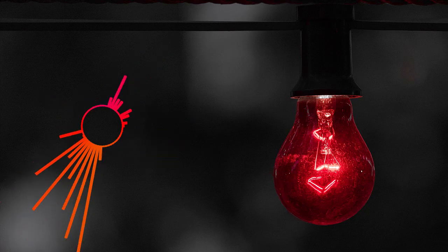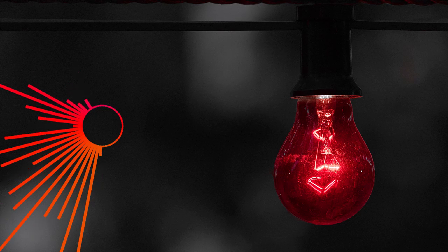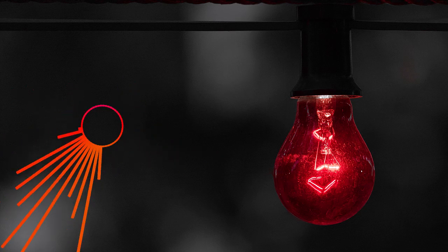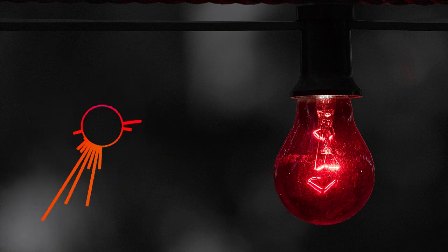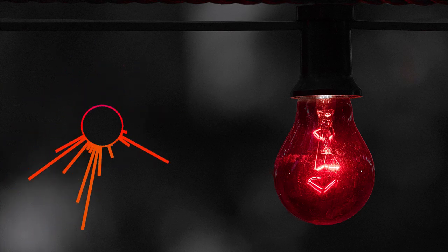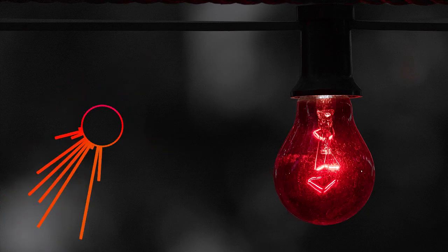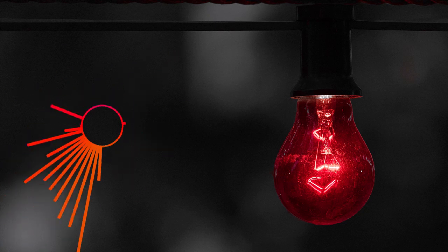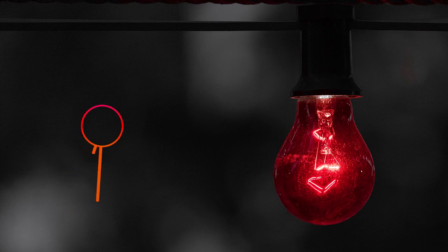If you replace a fluorescent lamp with an LED, do you still need the ballast? Can you wire an HID fixture directly to power? What kind of driver does that new LED strip need? These are real questions you'll face, and your understanding of the four lighting types will guide you every time.